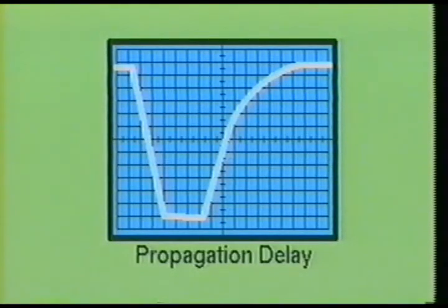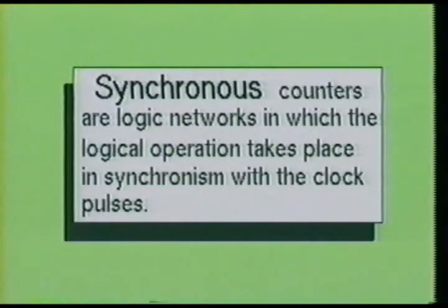All logic devices will contain some propagation delay, and this becomes a problem when the stages are wired in series, because the delay times are cumulative, in that the delay time of each stage in the series design will add to the total circuit delay. This problem is overcome by the use of synchronous or parallel counters. When wired in the synchronous configuration, all flip-flops are triggered at the same instant.